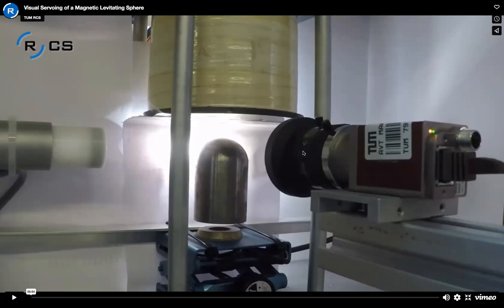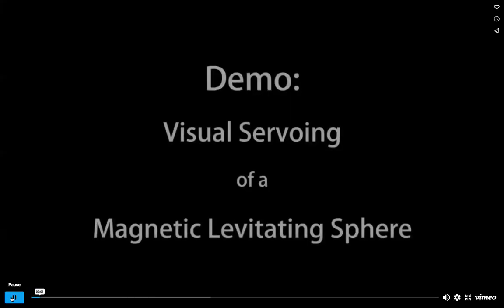This camera is a gigabit Ethernet camera, so it captures a very large number of frames with high resolution, and these frames cannot be processed in software. This is way too much data, and the timing constraints that we have are so stringent that you cannot process this in software, but this processing is happening on an FPGA board in hardware. And then based on the location of the ball, or the position of the ball, the magnetic field is adjusted in real time. So let's have a look at this.